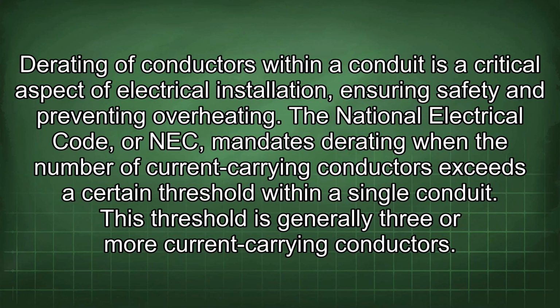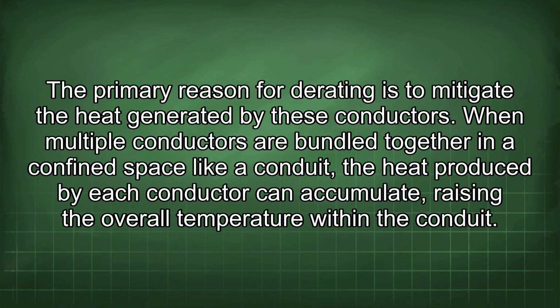Derating of conductors within a conduit is a critical aspect of electrical installation, ensuring safety and preventing overheating. The National Electrical Code, or NEC, mandates derating when the number of current-carrying conductors exceeds a certain threshold within a single conduit. This threshold is generally 3 or more current-carrying conductors.